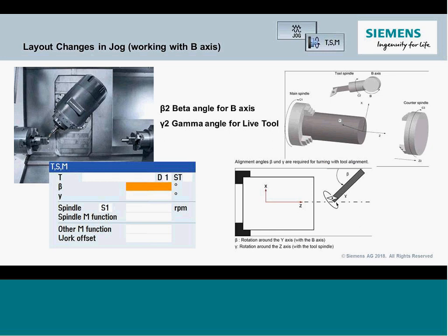But if I want to take that same tool and now come down the face of the part, I may want to invert it at an angle greater than 45, probably all the way to 90. Past that point, my insert is pointing the other direction. This is a right-handed tool, so I spin my gamma, or my spindle, around 180 degrees just by inputting a value of 180. And the system now allows me to put the tool in such a fashion that I can come down. What's nice about the system is it's going to track appropriately, handle the spindle directions based on the orientation, and also dynamically adjust for your offsets based on this orientation. But you have to use the beta and the gamma fields to drive this.